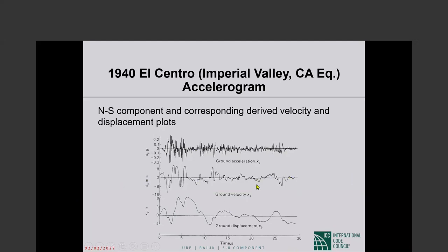And then if you integrate the velocities with respect to time, you get the ground displacements. The movement in terms of displacements is downright ponderous. It's a far cry from the acceleration plot. Here they're going back and forth, but it takes its own time doing that. Although this is one specific example, most of the things I said are pretty typical of earthquake ground motion.